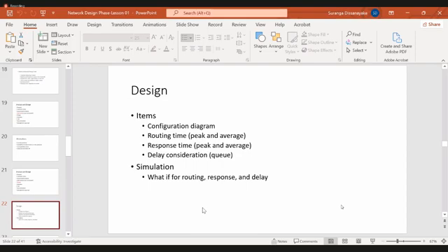The operator will come and do a feasibility study with a simulation. What they do is place one tower close by your university and place 3 antennas on top of the tower, and they run a simulation. Based on the simulation, they can get an idea of what coverage area can be produced with this site. Let's say the simulation has predicted 1 kilometer of coverage, meaning it is possible to produce a coverage with a 1 kilometer radius.